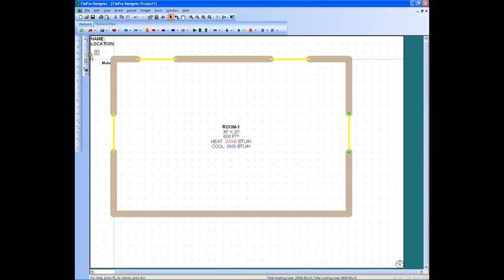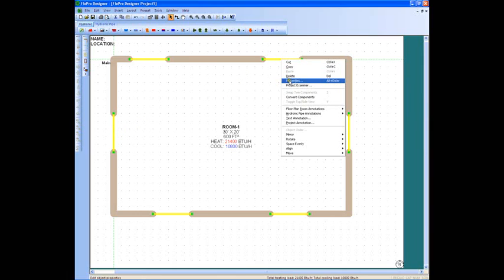And we'll get a couple more windows and throw them down here. And as we put these holes in the building, we can see that our heat loss is increasing. We're now up to 21.4. So now we're going to edit the windows. So we'll hold down the control key, we'll click on a window, another one here. We'll click on each window as we go, and when we right click on any window, it doesn't matter, we're going to be editing them all.